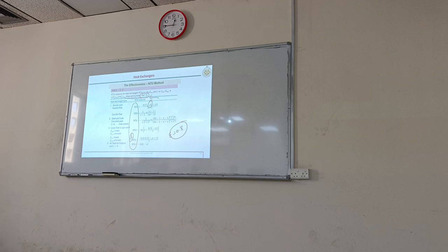We can cross-check our LMTD method. Yes, we can check, definitely, and those have been checked, don't worry. That's why these things are in the textbooks. So the previous table gives us effectiveness when NTU is known. This table gives us NTU when effectiveness is known. C, the specific heat ratio, is definitely known to us.